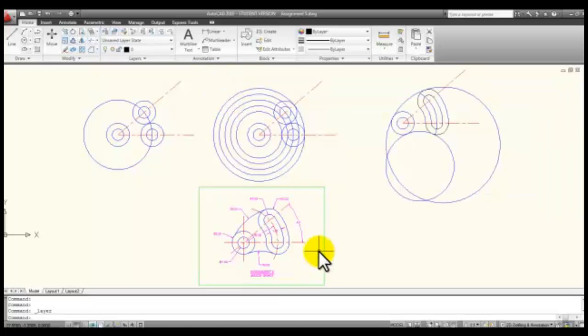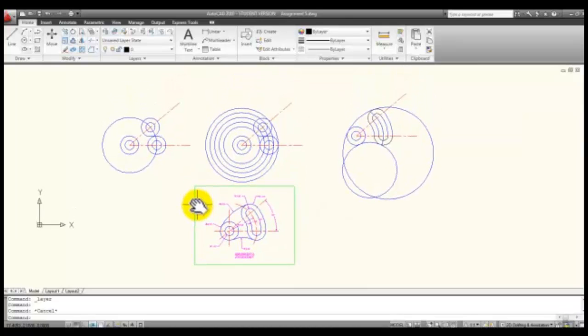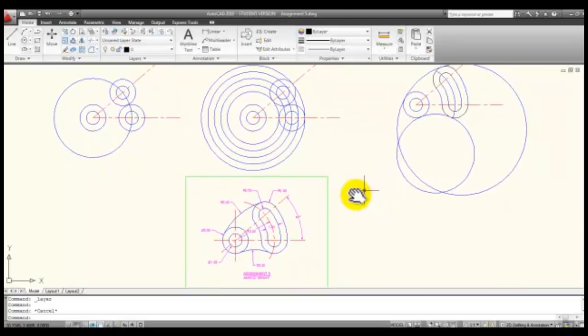Now, by now you know that you can draw either a rectangle or use lines to draw the border that's 11 by 8.5. Looking at this exercise, which is in the book, you can see that we have several circles that we're going to be working with. I've given you a step-by-step if you'd like to use this as a way of drafting your objects. You can start by creating these two smaller circles here, and be careful that you're using diameter and not radius. The two circles at the bottom left here are diameter.